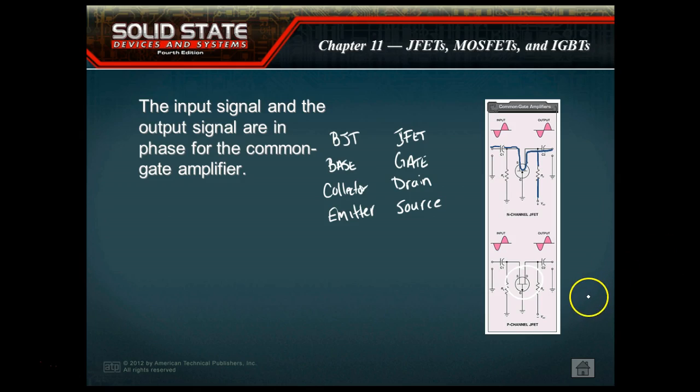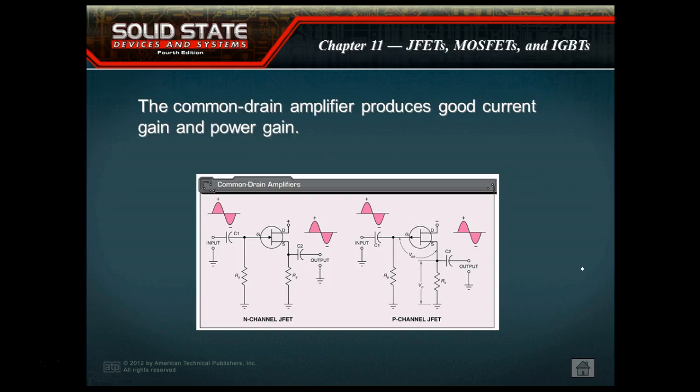So there's a lot of advantages to these things, and they have an extremely high input impedance. So we'll find out that these guys are used often on signals that can provide almost no current at all, like antennas and stuff like that. If you ever looked at the schematic of a radio, like a car radio, odds are the first transistor you're going to see is going to be an FET, and then we'll start running into bipolars, and we'll look at some of those advantages in a minute.